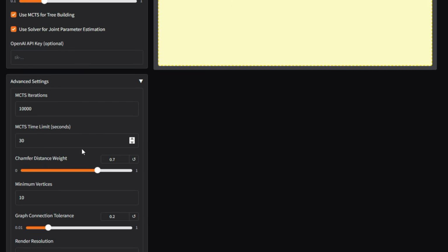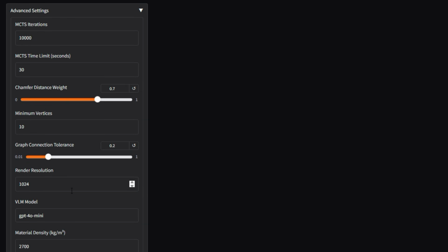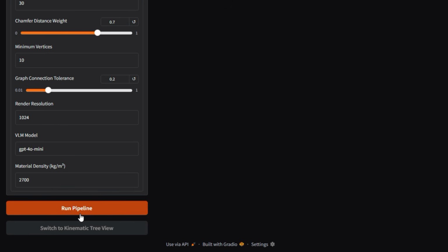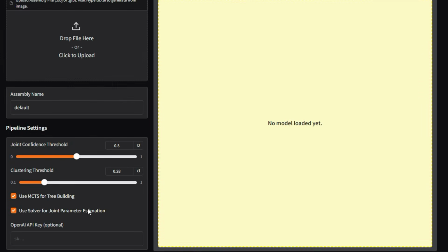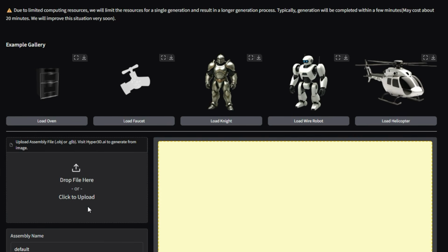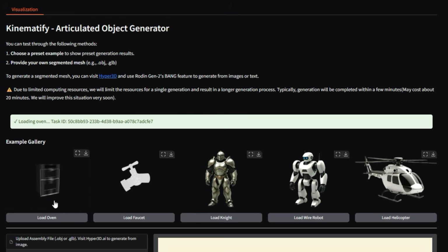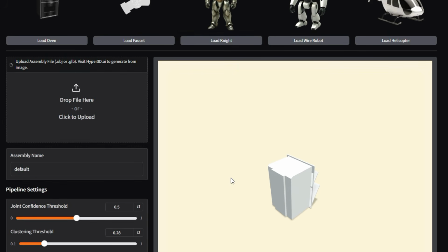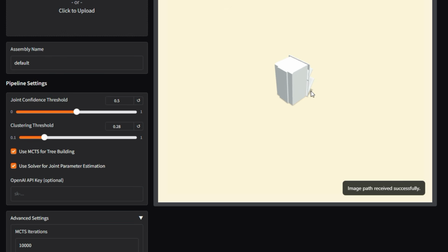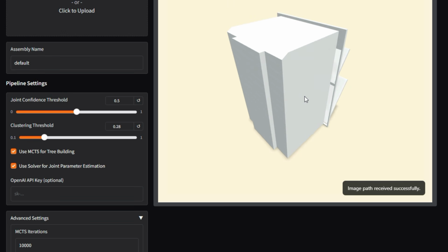automated framework that synthesizes articulated objects directly from RGB images or textual descriptions, tackling the hard problems of inferring kinematic topology and estimating joint parameters from static input. It combines a 3D foundation stage that segments geometry, a search step based on MCTS to recover a plausible kinematic tree, and a geometry-driven optimization stage that refines joints into a usable, collision-aware structure.